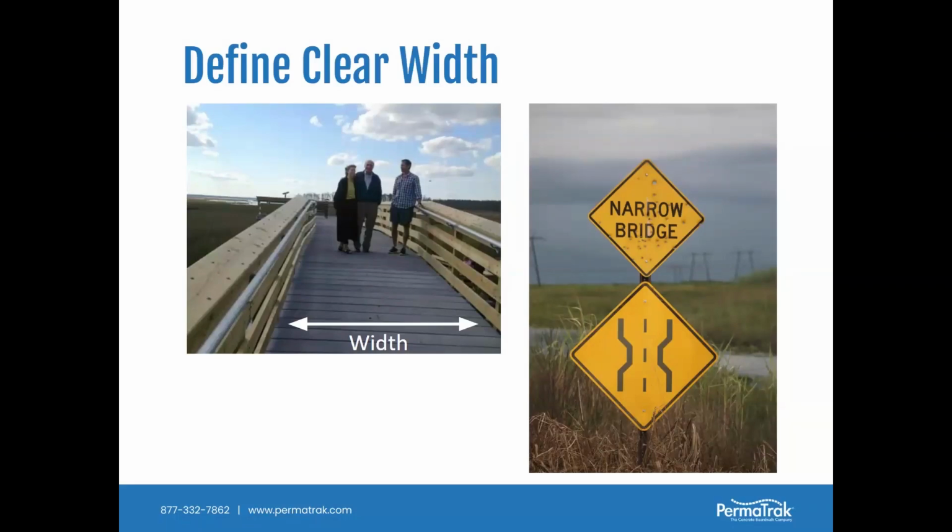Because what we're trying to avoid is what you see in the right-hand side picture, a narrow bridge. You certainly don't want to take your trail and then neck it down when you get to the bridge and then widen it when you come on the other end. We have made that mistake. We've learned the hard way, but it's good advice to take your trail width and make it exactly the same as the clear width on the boardwalk. At least no narrower on the boardwalk than the clear width matching the trail.